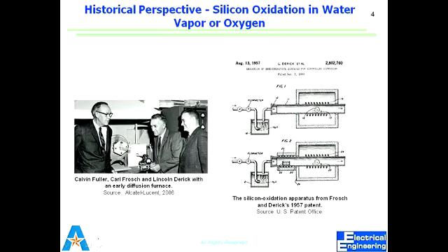The oxide is done using a furnace where we control the temperature and the content of oxygen. We can bubble oxygen through water and do what we call wet oxidation, or we just supply oxygen with nitrogen. So what is that process fundamentally? Where do we see that process happening? Oxidation. When we see rust, right? But in this case, we are using it to change silicon into silicon dioxide, and we want to achieve a very controlled layer of silicon dioxide.